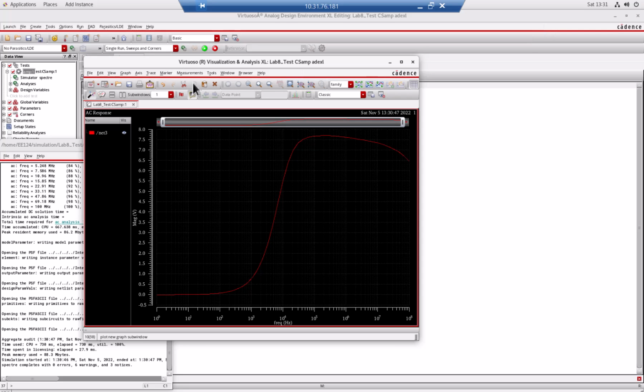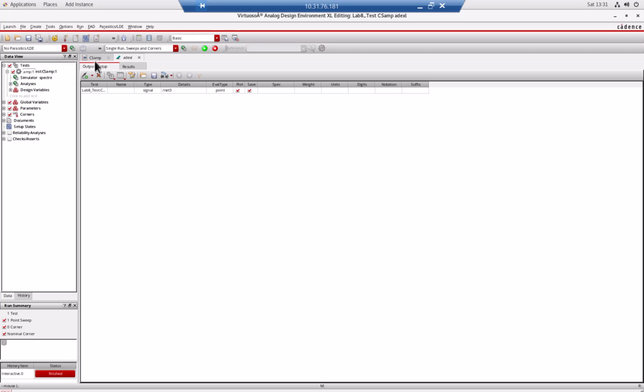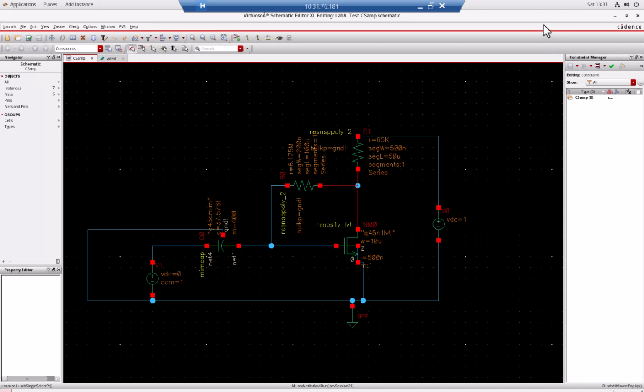We can look at the circuit. We'll go to the top CS amplifier. This is because at low frequency, you have a large potential drop across this capacitor. Okay, remember this one is tied to the drain, so this is not infinity. As a result, when you have a large potential drop across this one, you actually get smaller voltage applied to the gate. So that's why the overall gain is smaller.